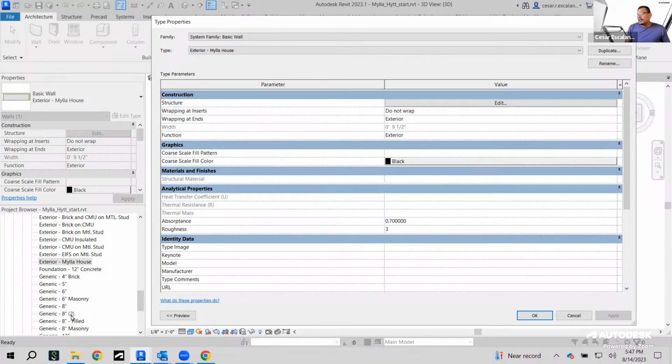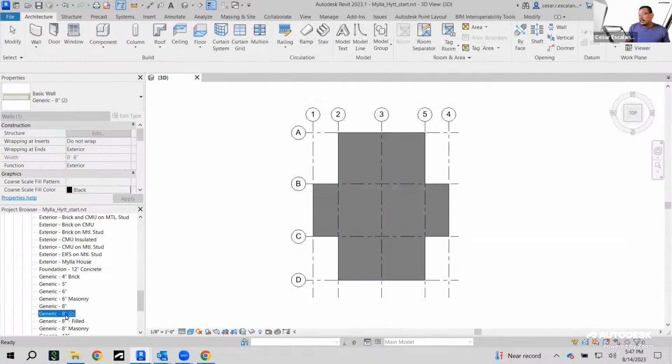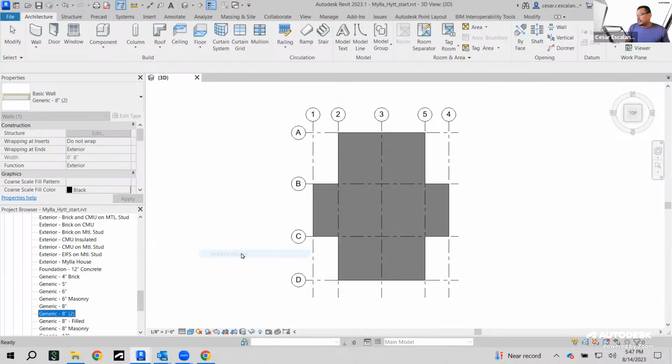And you can actually see the usage of a family. If you select a family in the project browser and you say select everything in the project, the filter in the lower right side is going to list all the elements in the project that are part of that type. And so if this is not in use and is redundant and doesn't make any sense, you can delete it, right? But thanks for the comment. That's true for every family in the project.